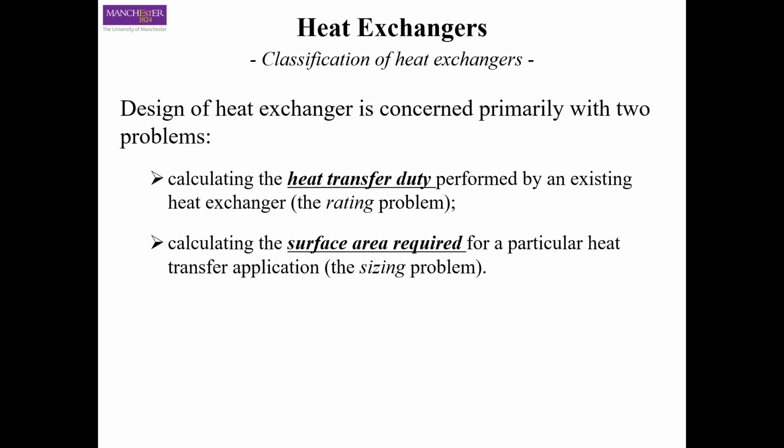In terms of the design of heat exchangers, we are primarily looking at two things. One is that, let's say you already have an exchanger and now you have changed the temperatures or conditions of the process, and you want to see if the old heat exchanger would be good enough for the new conditions. In that case, we calculate the heat transfer duty of this old heat exchanger to see if it will fit the new conditions, and that's what we call the rating problem.